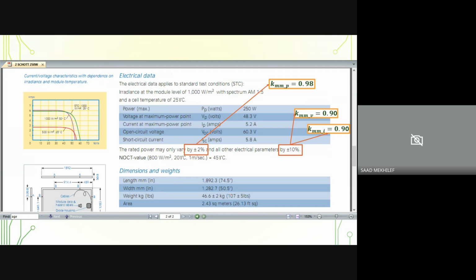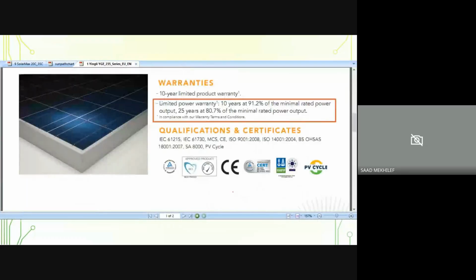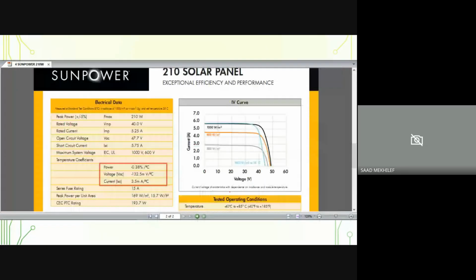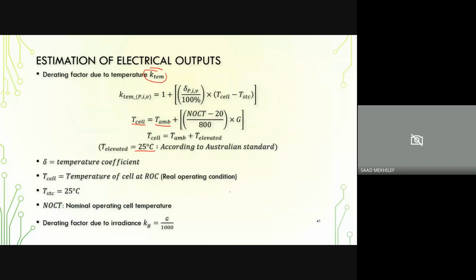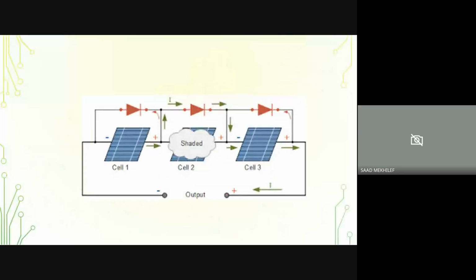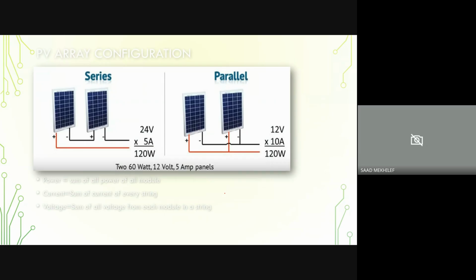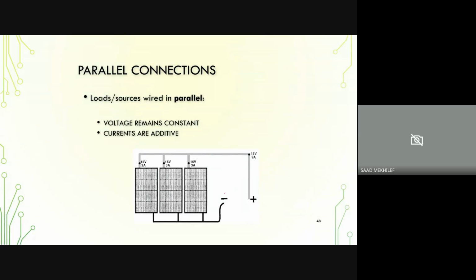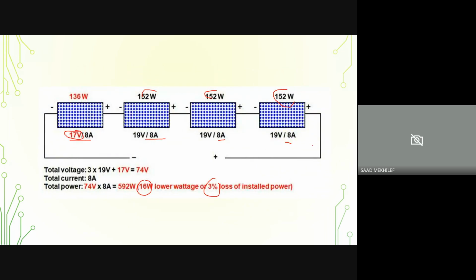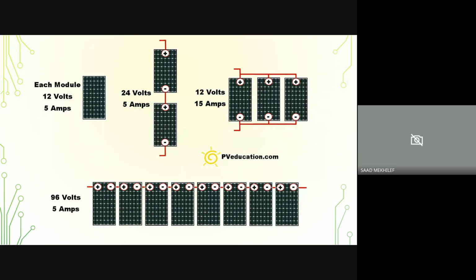The manufacturers always protect themselves with this plus minus 2%. So this is to protect themselves, because yes, it's 19 volt, but plus minus 2%. If we see 1%, actually you're talking about 0.2 volts. Okay. So this is the effect when we have a panel mismatch. And the same thing applies when we connect panels in series and parallel. This is actually straightforward.